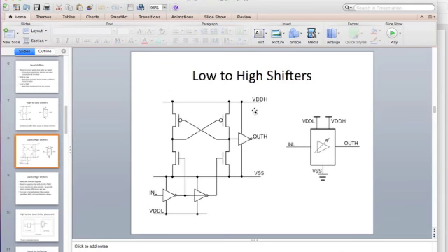Now this works very well when the high and the low voltage levels are not too far off. Then this is good enough and it does the job. The problem comes when the voltage at the low level is extremely low, especially down close to the subthreshold regions, where the drive for the PMOS becomes so weak, because the voltages of these inverters is just VDD low, which is say near subthreshold or near threshold, 200, 300 millivolts. Whereas this high voltage could be the nominal voltage 1 volt, probably even 2 volts for the IO interfaces and so on.